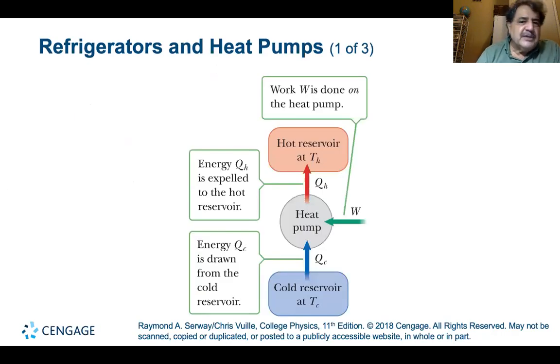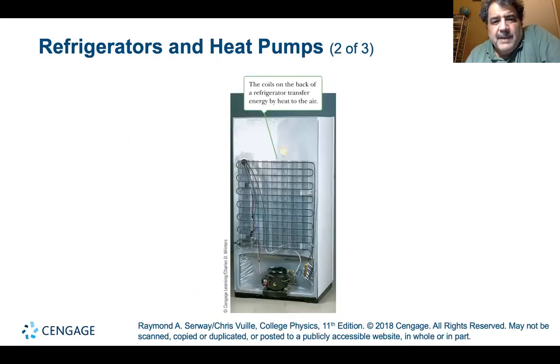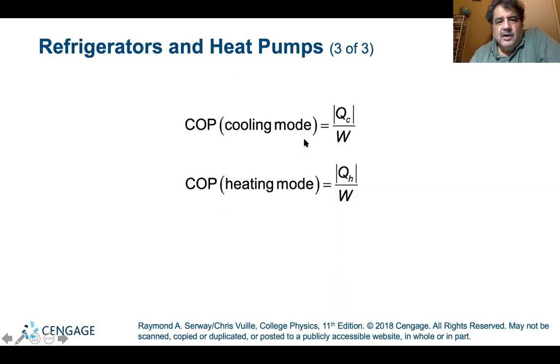Okay, refrigerators and heat pumps. Work W is done on the heat pump, so energy Q hot is expelled to the hot reservoir, and energy Q cold is drawn from the cold reservoir. In a refrigerator, the coils on the back of the refrigerator transfer energy by heat into the air. So this is the hot reservoir. Of course, the inside of the refrigerator is the cold reservoir.